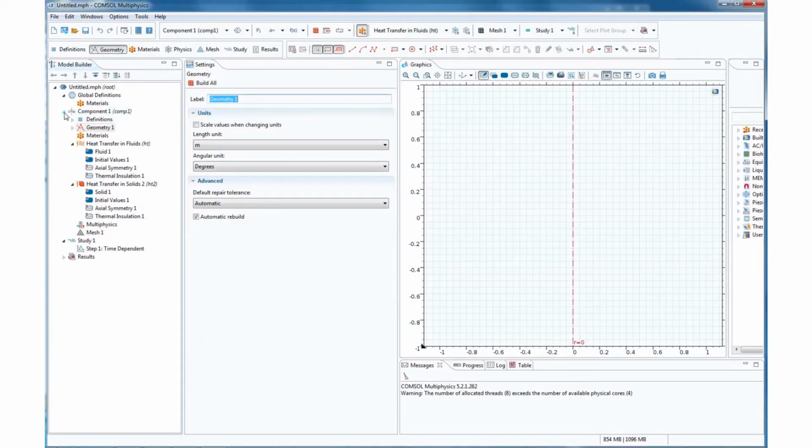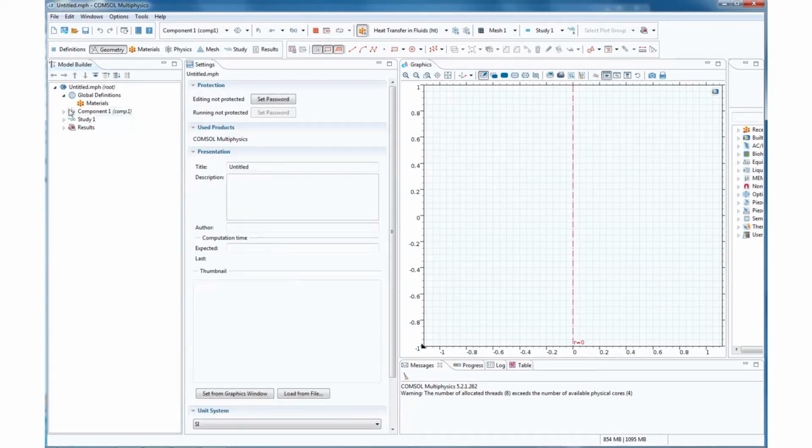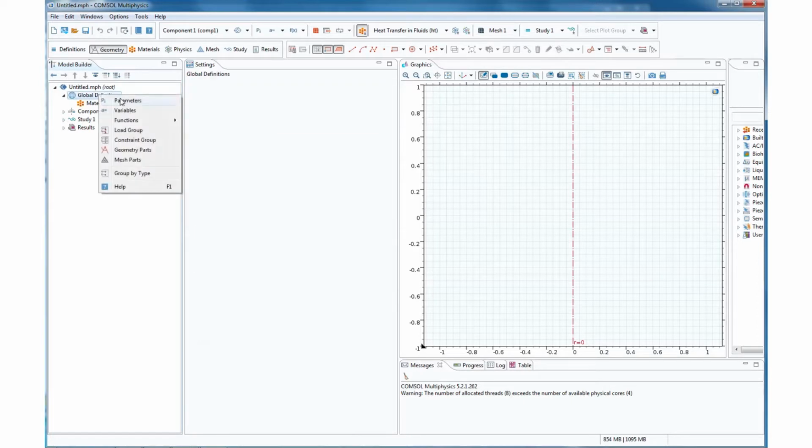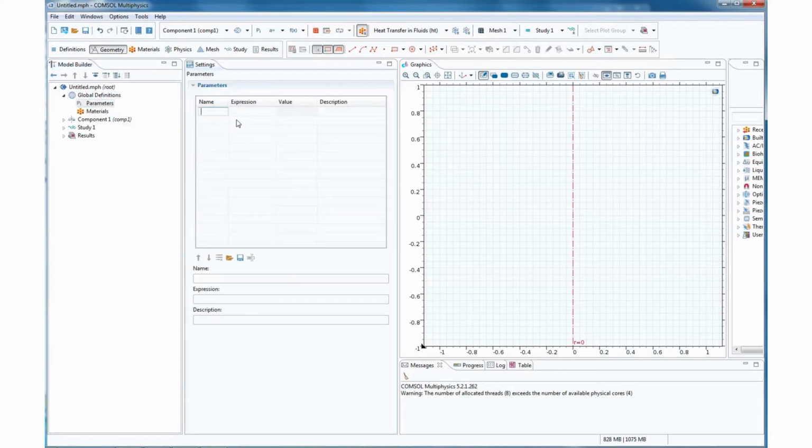And I close some things here just so you can focus on what we're actually doing. You right click, hit parameters. This is just a list of numbers. It's like variables in coding. I think it's just phrases that mean numbers basically, because you don't have to say units. You can just type them here so it's easier to get to them later.